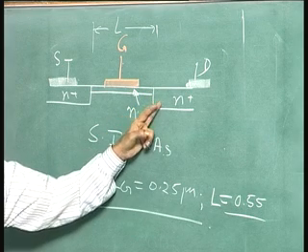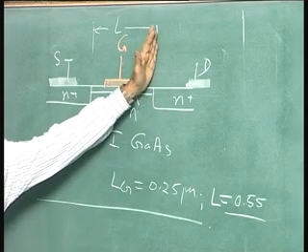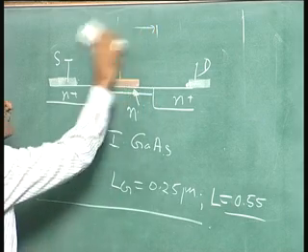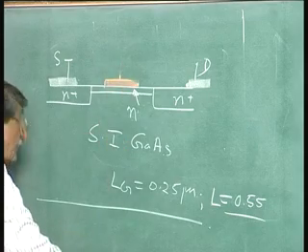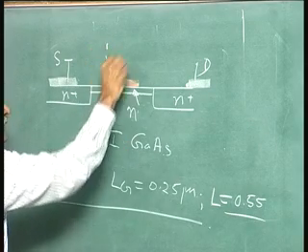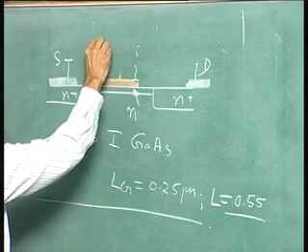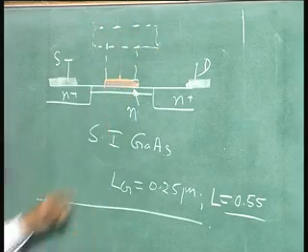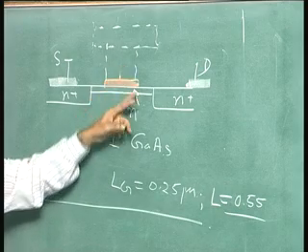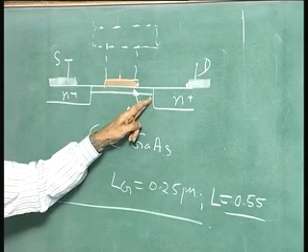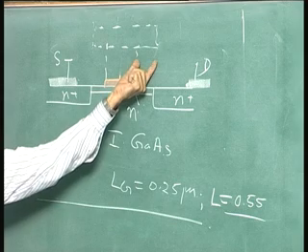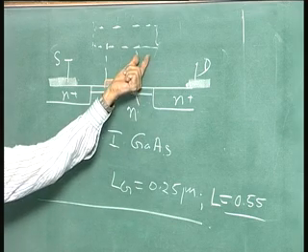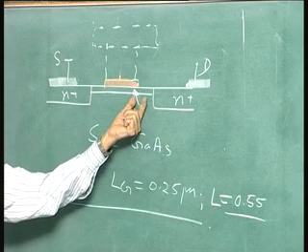this layer was implanted through the mask on the top. Okay. The layer was implanted like this. There was something on the top, and this is just I am projecting because it was there when implanted. That is putting a dotted line. So, the layer was implanted using that mask. So, if this undercut is 0.3 microns, that is located away from that point. If it is 0.15 micron, that is closer.